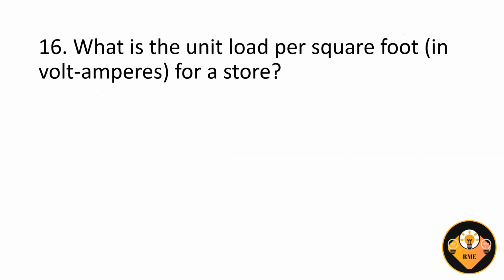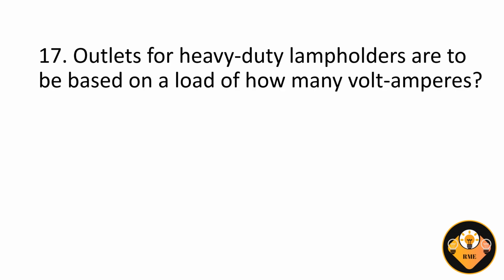Number 16. What is the unit load per square foot, in volt-amperes, for a store? The answer is, 3 volt-amperes. Number 17. Outlets for heavy-duty lampholders are to be based on a load of how many volt-amperes? The answer is, 600.